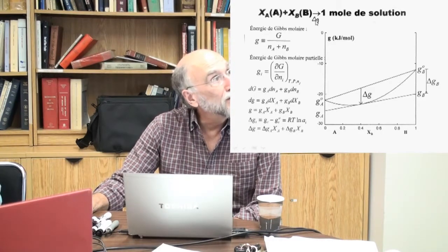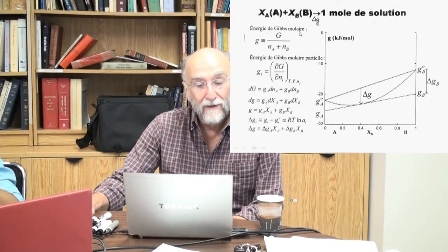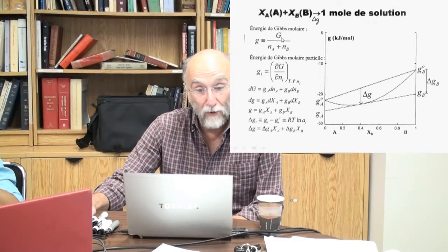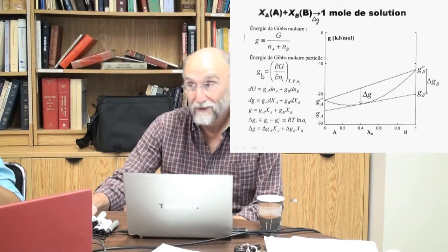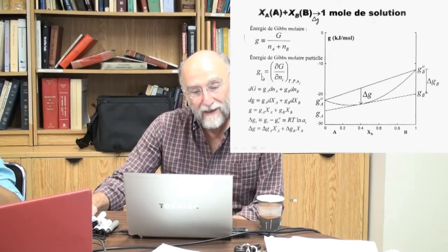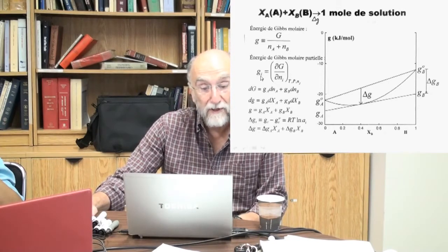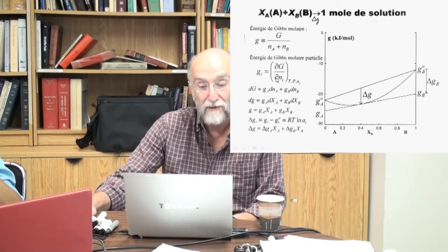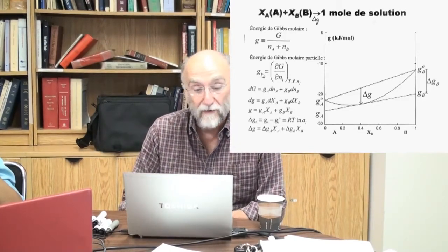Taking the integral, not the partial, you're taking the whole: pure A, pure B, and you're mixing them at constant T. So that's the integral molar Gibbs energy of mixing. The molar is equal to the total in joules over the total number of moles. The partial molar Gibbs energy of I is dG/dNi, and this is also known as chemical potential. In this chapter I talk a little bit about GI, but mainly I use μI now. This is chemical potential. The partial properties are very important because of the prime importance of the chemical potential as a potential for transfer of A.